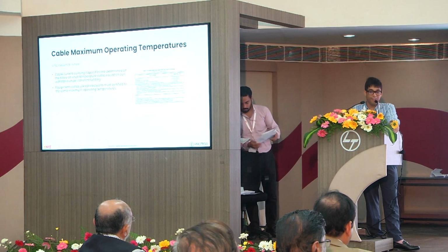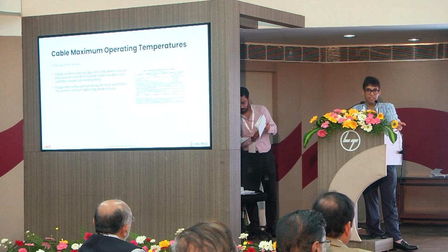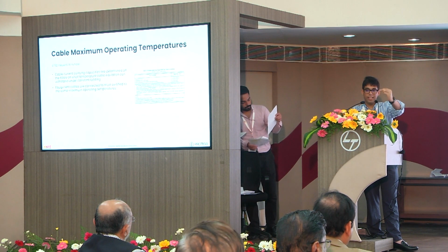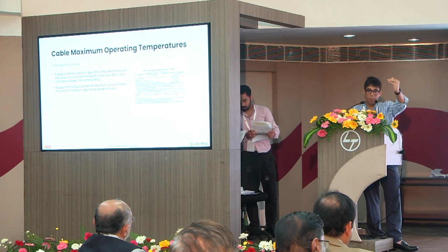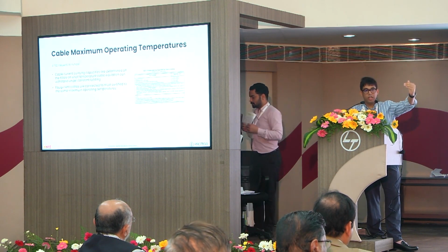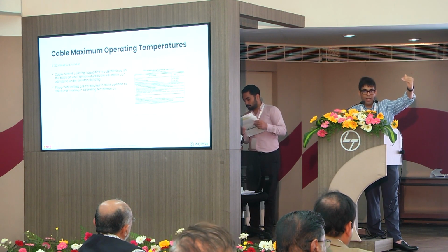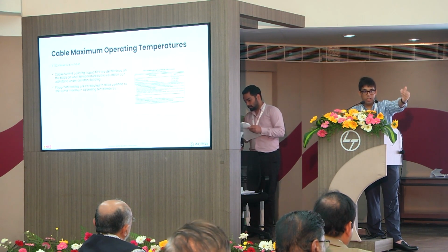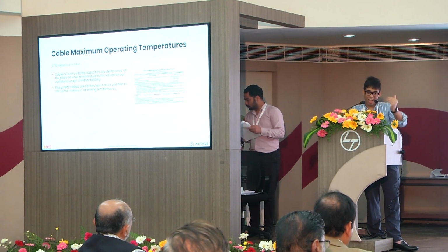You have to look at the 70 degree current carrying capacity, because obviously we know that as the cable carries more current, it heats up. Granted, the insulation in 90 degree cables can handle up to 90 degrees, but can the terminals, can the equipment handle it? If we do not know, then we have to derate.